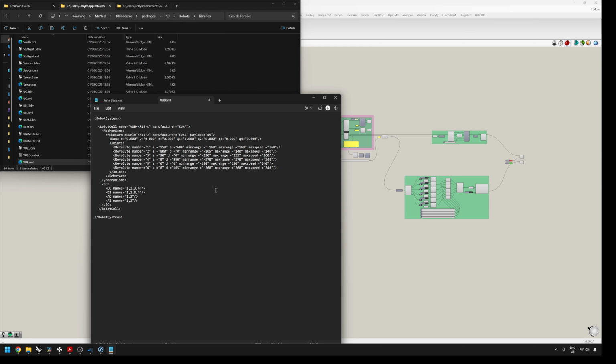Another concern is that the XML only accepts 2 DH parameters per joint, A and D. This may be a problem by itself, since the plugin could be applying additional manufacturer-specific conventions internally. However, those settings are neither visible nor adjustable, so it is unclear whether using an ABB or KUKA template introduces offsets or axis conventions that do not apply to the Kawasaki FS45N.